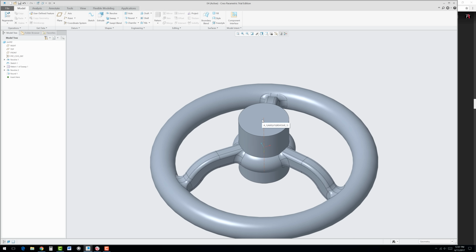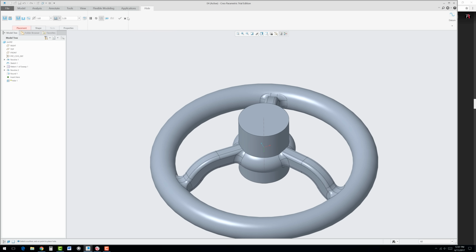And now let's go ahead and we're going to put in a hole. So using the hole tool versus before we've always learned how to draw a hole in with the sketch. But if you go to hole here, you could go and select, use standard hole profile, and let's go with a counter bore.